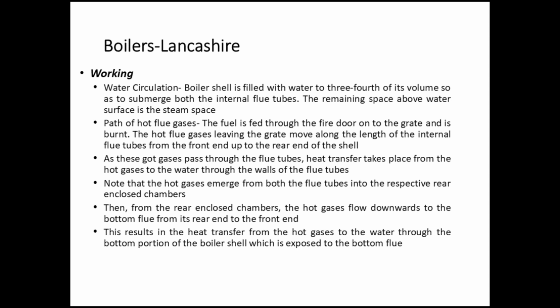Note that the hot gases emerge from both the flue tubes into the respective rear enclosed chambers. Then, from the rear enclosed chambers, the hot gases flow downwards to the bottom flue from its rear end to the front end. This results in the heat transfer from the hot gases to the water through the bottom portion of the boiler shell, which is exposed to the bottom flue.